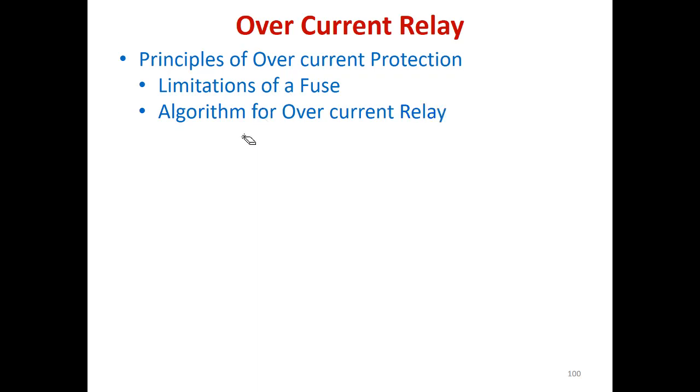Then the algorithm for the overcurrent relay. We'll talk about a simple algorithm, which is in fact the basis by which overcurrent relays are designed. Then we'll see the time multiplier setting. This plays a very important role, and we'll talk about how it sets the delays in the overcurrent relay.